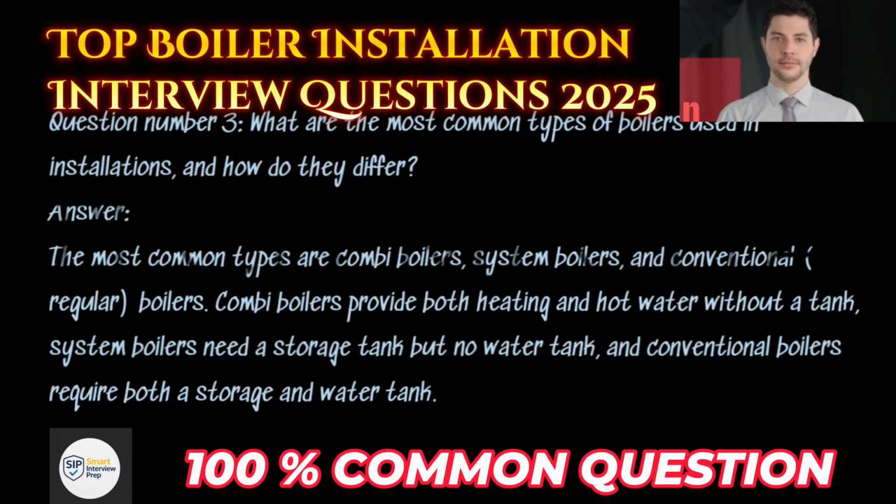Question number 3. What are the most common types of boilers used in installations, and how do they differ? Answer. The most common types are combi boilers, system boilers, and conventional, regular, boilers. Combi boilers provide both heating and hot water without a tank. System boilers need a storage tank but no water tank, and conventional boilers require both a storage and water tank.